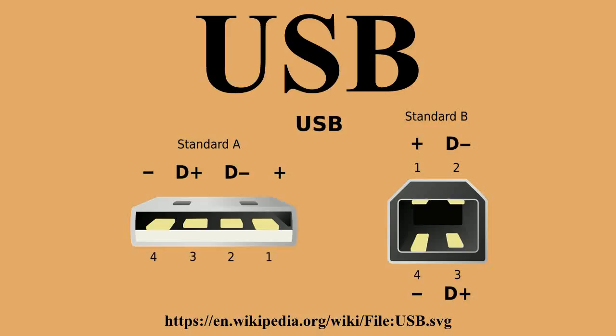When a USB device is first connected to a USB host, the USB device enumeration process is started. The enumeration starts by sending a reset signal to the USB device. The data rate of the USB device is determined during the reset signaling.